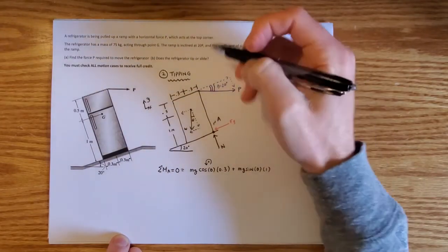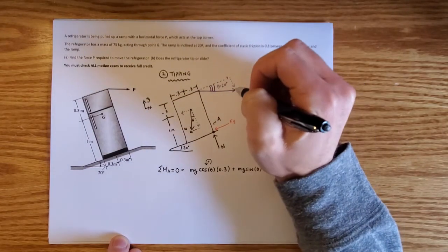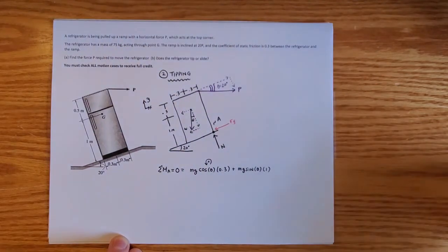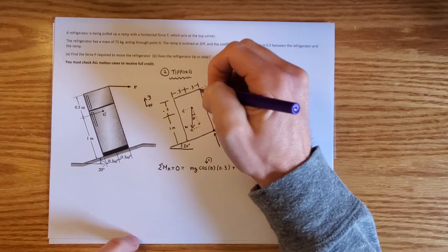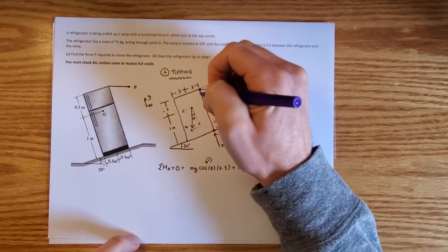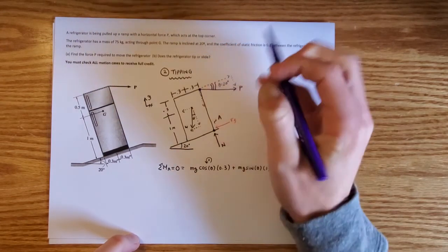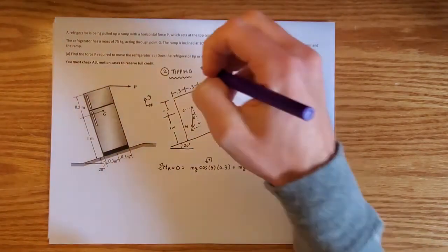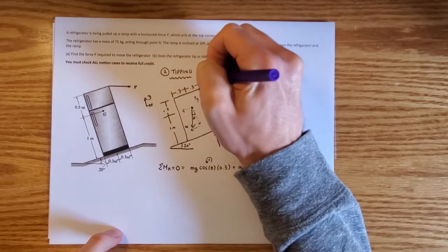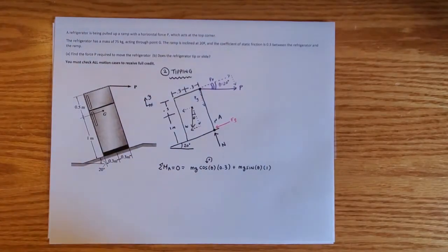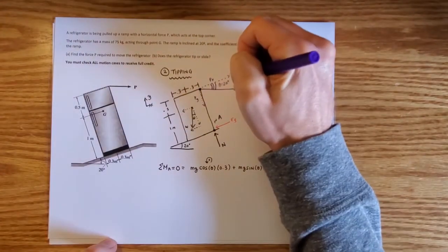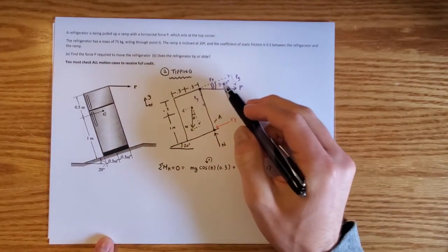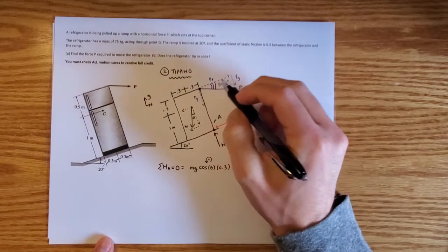And last but not least, we're going to have to account for the effects of P. Well, this vertical component of P looks like it's having something going on in this problem, but remember, this P is really acting from this point. So that P would actually go through point A. So we don't consider Py, we only consider Px. And I'll just draw Py here as well so that's clear. So we only consider Px, which is P times the cosine of 20, and that's the tipping force.